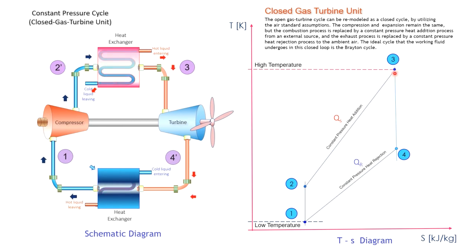From state point 2 to state point 3, the air goes into a heater, where you have heat addition to the air. It undergoes a constant pressure process, so this is a constant pressure line. You have heat addition because the direction from point 2 to point 3 is of increasing entropy as you measure from the origin. Increasing entropy means you have heat supply.